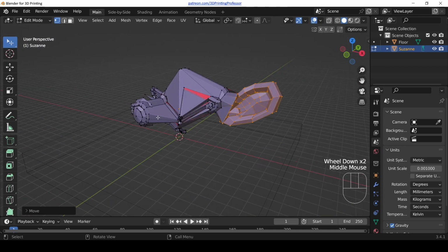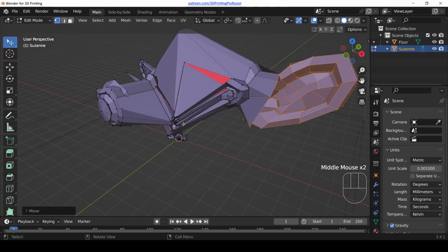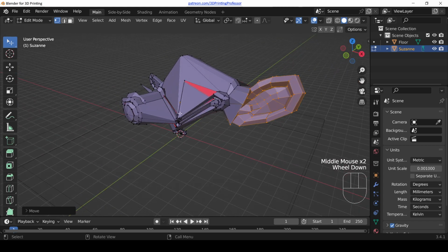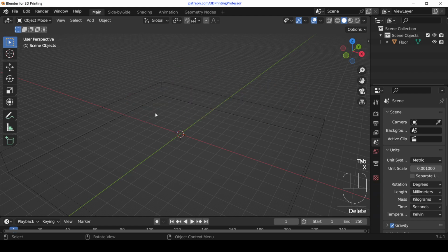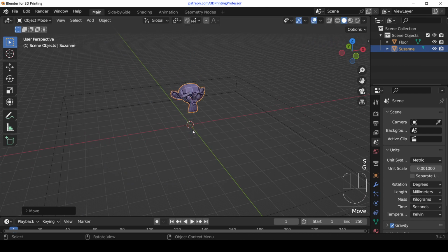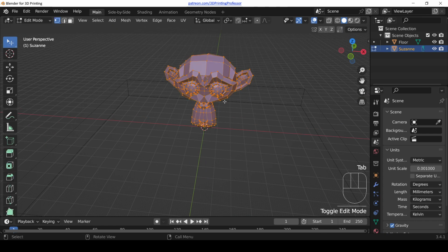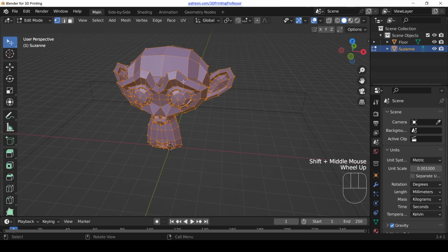You can do anything. And in fact, I'm going to call it here and give you guys a little bit of homework to work on. So here's what I want you to do. Basically, I want you to do everything that we did in this video. Add a monkey in, size it so that you can work on it a little bit. Go into edit mode, and use the tab key to go into edit mode. Switch between vertex, lines, and face select with the 1, 2, 3 key on your keyboard.